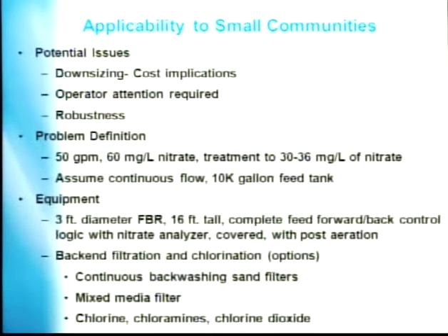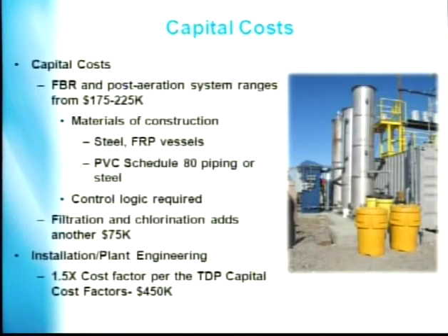You can have various forms of back-end filtration and chlorination, and there are various options that you can employ. Probably you want to look for the least expensive one, and also the one with the least amount of operator attention, certainly. That's something we've worked with in many applications, so we bring that expertise. But at the same time, the utilities sometimes want a specific type of filtration or downstream chlorination or disinfection mechanism implemented.